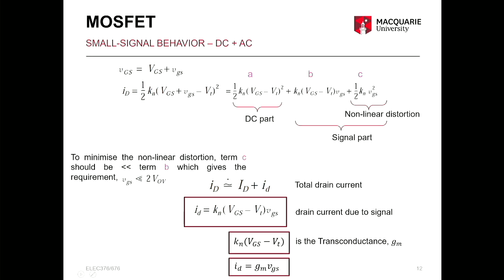Okay, so we have discussed this. Everything I write here, I included a slide with a proper, more neat writing. So this is our transconductance, or GM. And this formula we can write as ID is equal to GM VGS, just like we saw before. So that's nothing but Ohm's law, where voltage is equal to resistance times current, or current is equal to voltage times conductance.